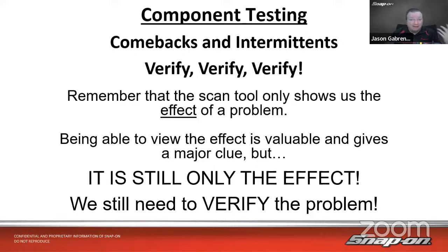I think back to my days in Subaru. I remember one time I had a car come in with a P0340 something. I think it was a cam sensor code, regardless. I don't remember the exact number, but it was a cam sensor code. And if you look through every line on that flow chart, not once does it ever say to test that sensor, look at the sensor, or replace the sensor.